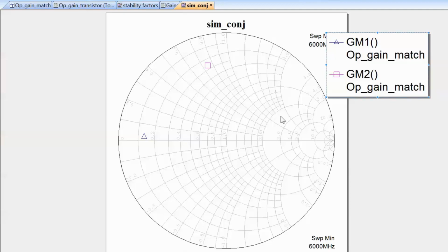In this tutorial, we will be looking at how we can adjust the mismatch at the output to be able to achieve a gain which is different from Gmax. And the way this technique works is that we choose a specific termination for the output which we want to use to achieve our target gain, and then once we've selected this termination and we've put it at the output of the transistor, then we look at the new S11 of the transistor, the new input impedance of the transistor, and we conjugate match it in order for this gain to be achieved.